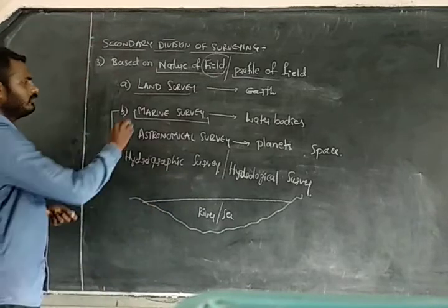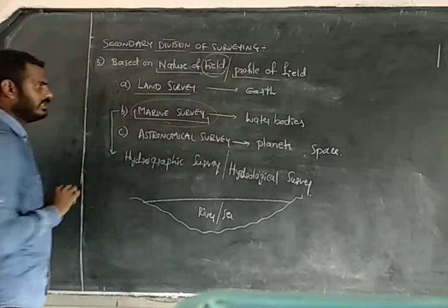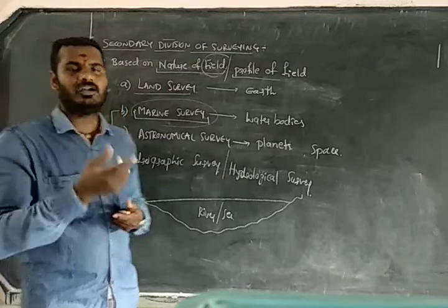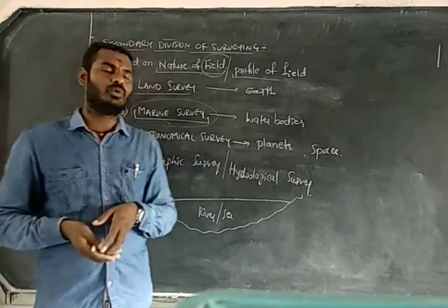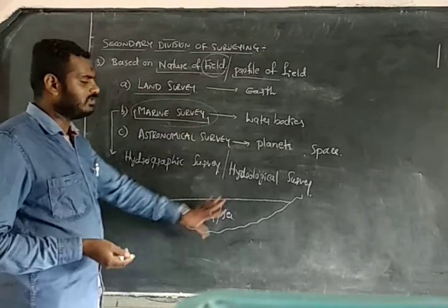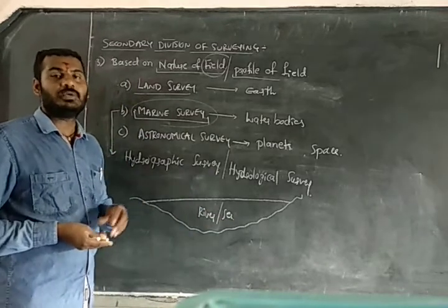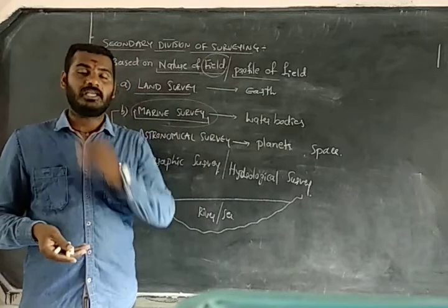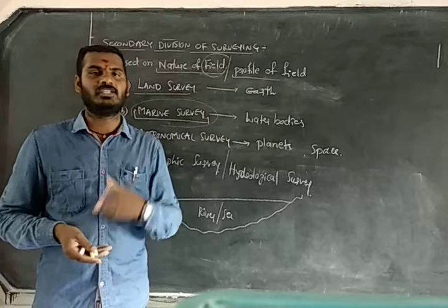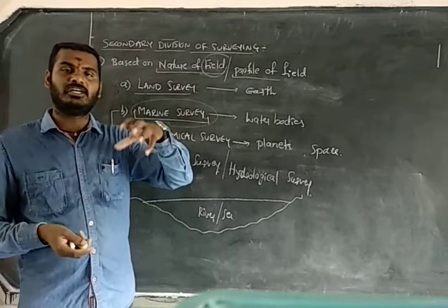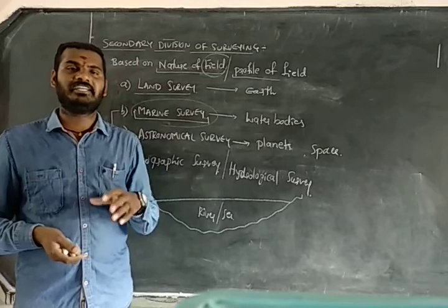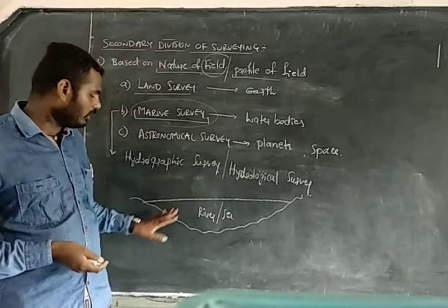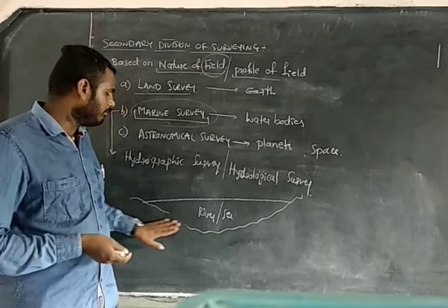That is why we go for marine surveying, which is especially useful for the construction of harbors and for knowing the depth of water available over the natural ground level to construct underwater structures. If you want to construct any underwater structure, it is very important to know the depth of water present there and what type of soil is present below the water level.